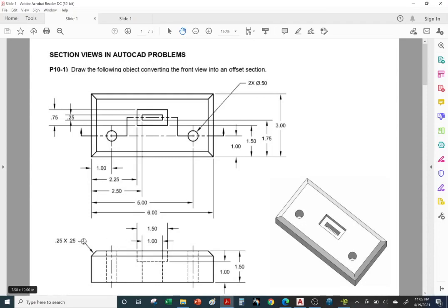If it's a circle inside of another circle, a little one and a large one, that means chamfer all over. That means all the edges, even the bottom ones and the side ones, will be chamfered. But in this case, we only have one circle indicating that we're just going around the top. Chamfers are to avoid having sharp corners.